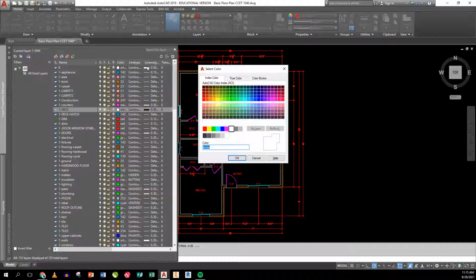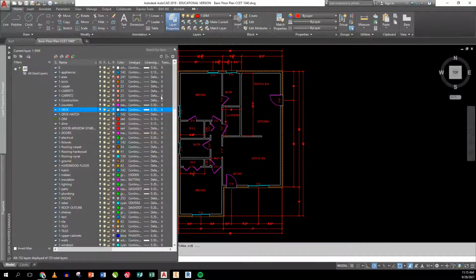And then I control the thickness of the line weights right here for plotting. I don't do a lot with that all the time. These are like, that's a 0.5 millimeter line for my white lines typically. Sometimes they do get changed up. This is a 0.3 millimeter line for, that's a doorway right there. So I work my way through those, okay?